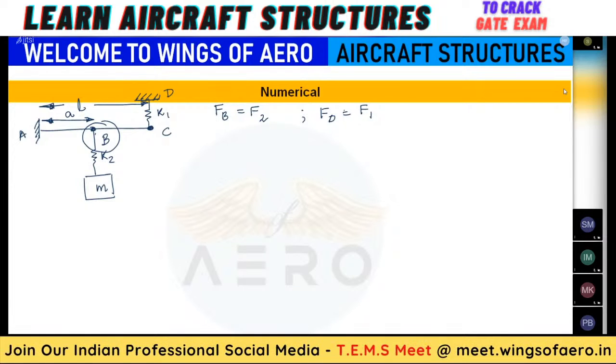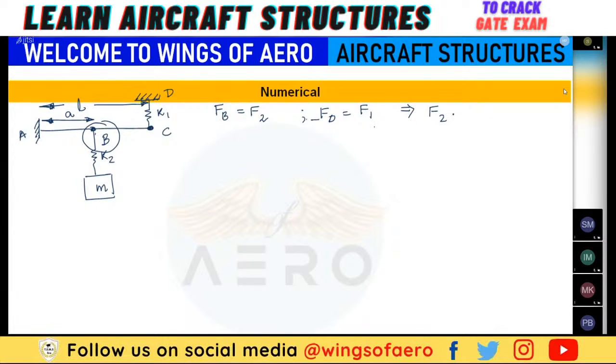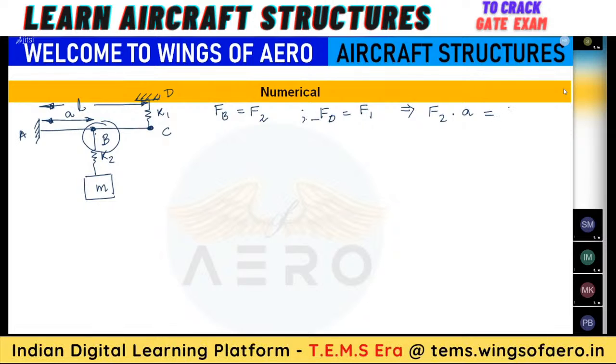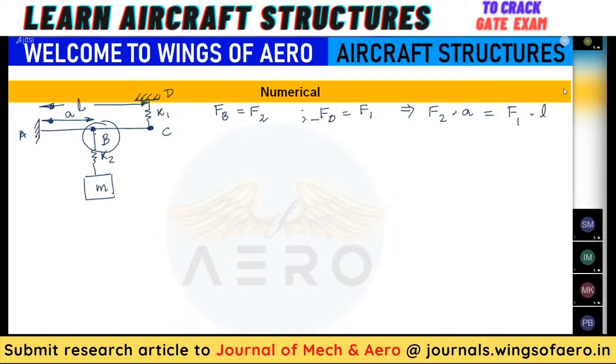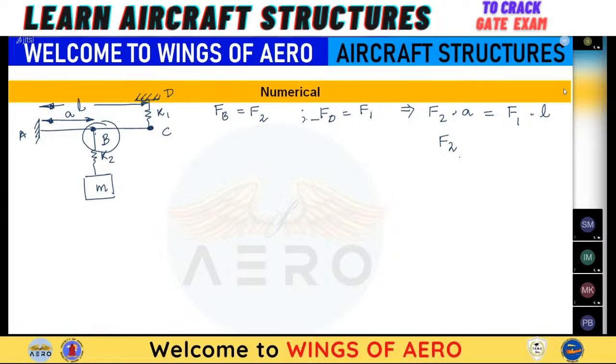Now in this situation we can write an equilibrium equation: the force at point B, F2, into the distance A, should equal the force at point C or D, which is F1, into the distance L. Either way I can find the force acting on any one of them.